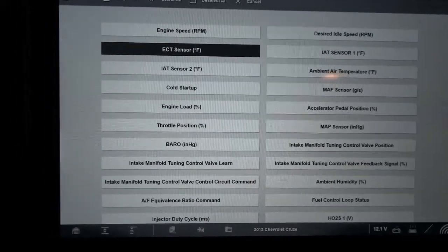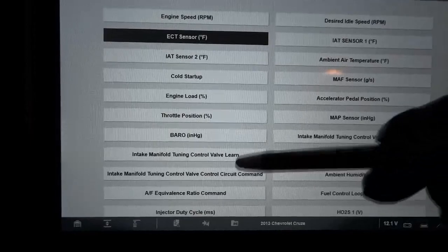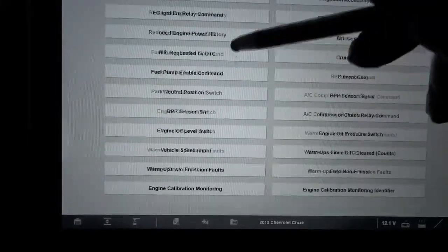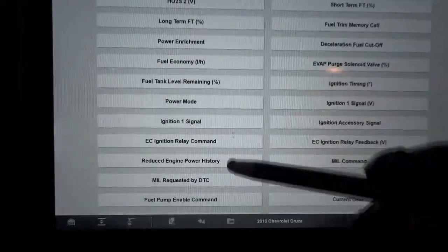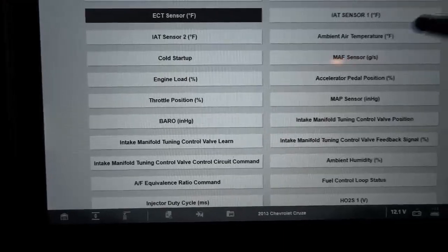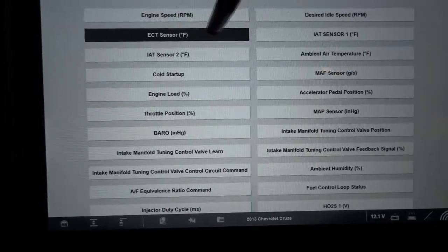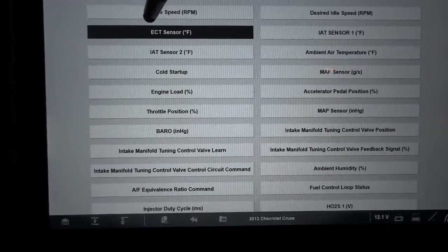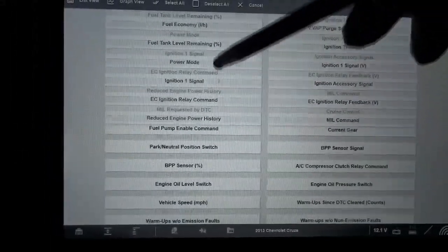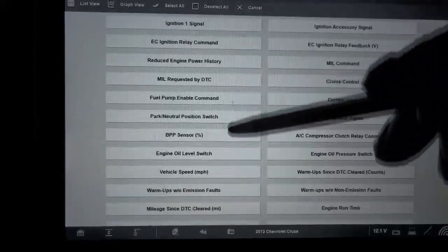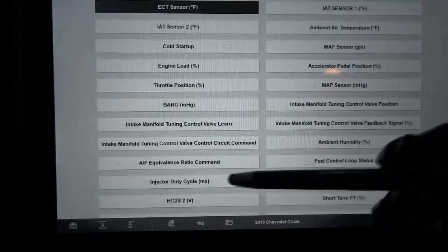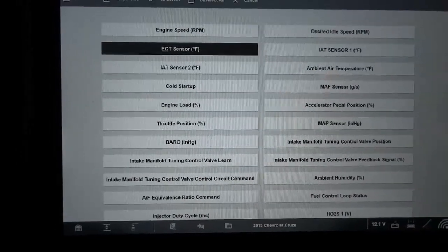So we have to see this coolant temperature increase up to, I guess, 195 before the thermostat opens, okay? And once the thermostat opens, we should be able to see a drop on the graph of this engine coolant temperature sensor data PID. And this will tell us whether the thermostat is working well or not. So that's all I want to look at for now.